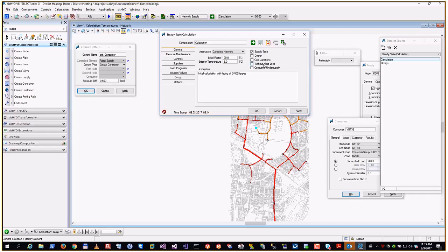Undersupply is when your network, for example, has too small diameters in pipes, and the demand is very high, and you have a high mass flow, then the pressure difference between supply and return, you get this situation. Ah, I got it. And then you get calls from your users: we are your user, but our water is not hot enough. We do not get enough mass flow to operate our heating. Okay.